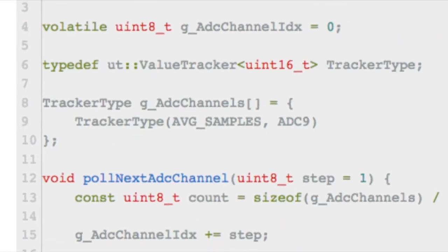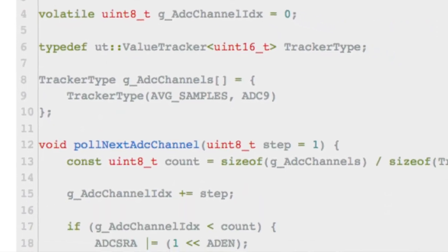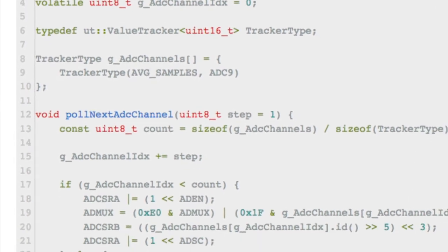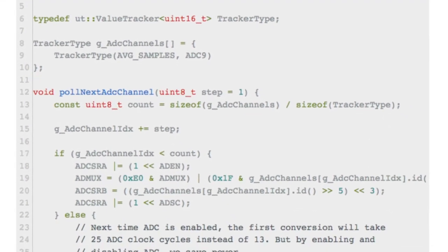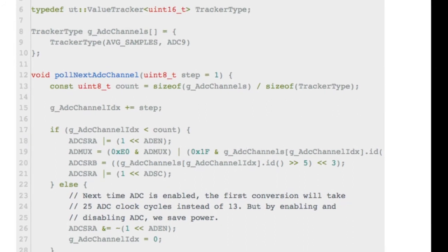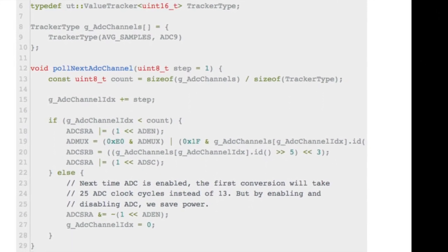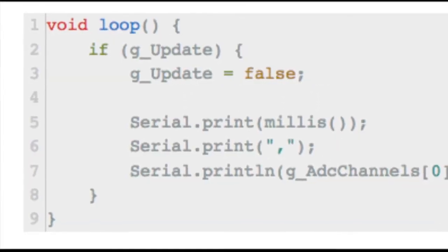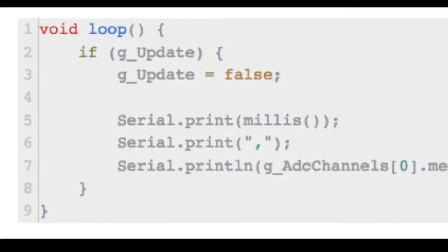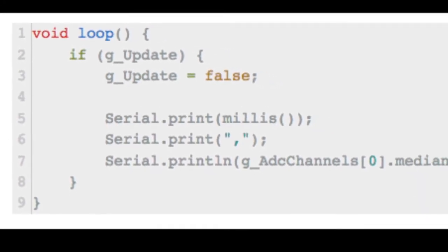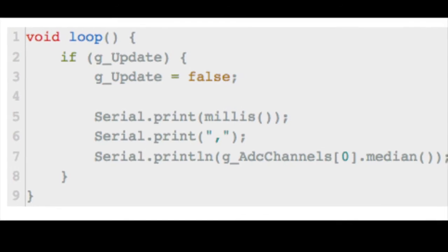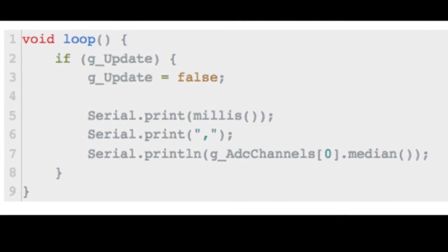At this point, I'm set up with a single analog sensor. But when I add more in the future, the function below will instruct ADC to sample from all configured sensors in turn. Every 50 milliseconds, the code in the main loop will compute the average and send the data out for analysis. In the example above, Arduino sends messages using the serial print function.